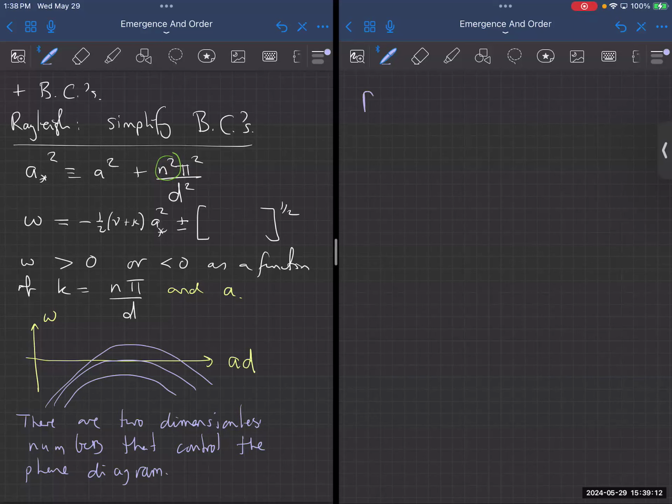One of these is called the Prandtl number, which is nu over kappa. Remember, last time we talked about the variables that prevent convection occurring. One was the viscosity of the fluid, one was the thermal conductivity. So this is the ratio of the two variables, the viscosity and thermal conductivity, that prevent thermal convection occurring.